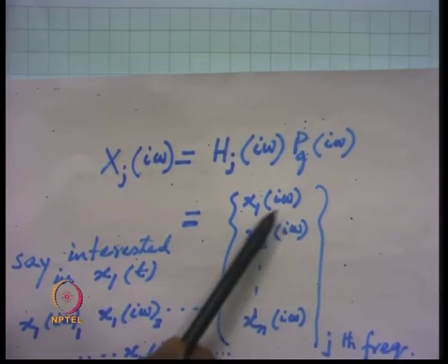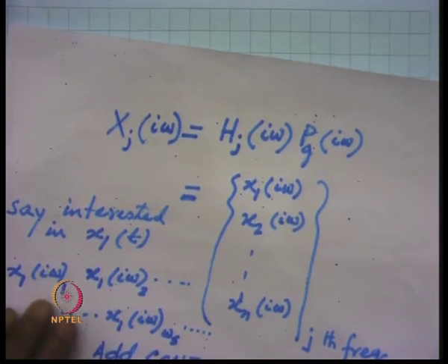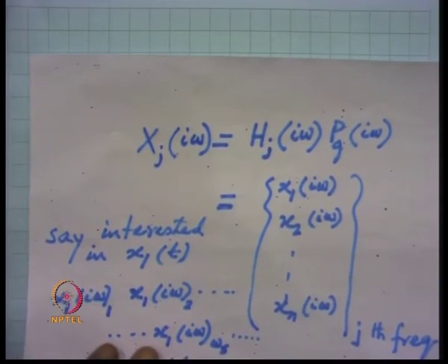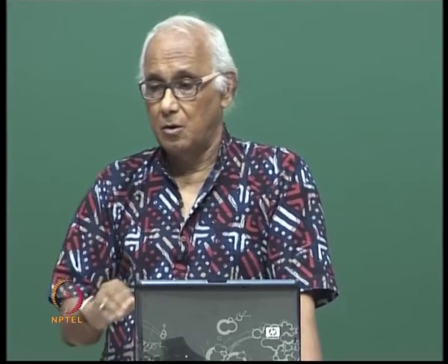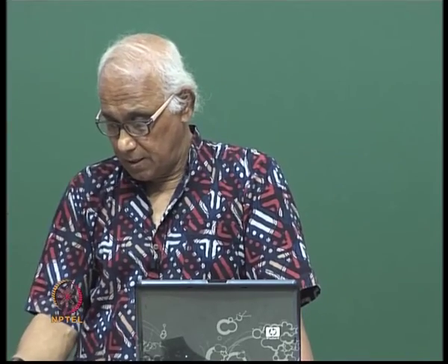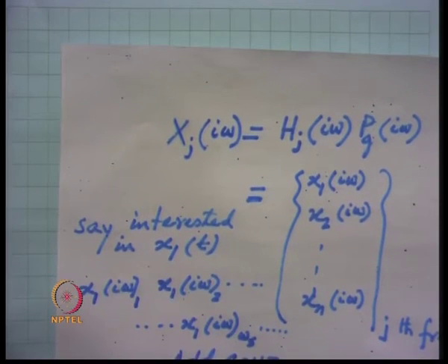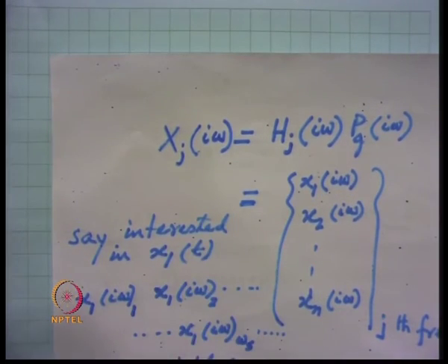Then each one of them can be taken out separately, and the first n by 2 plus 1 quantities of x can be written down and put in the FFT algorithm, and then we add to that the complex conjugates of them as I described before. Then we have the complete set of x1(i omega) for the response 1 and put it into IFFT.